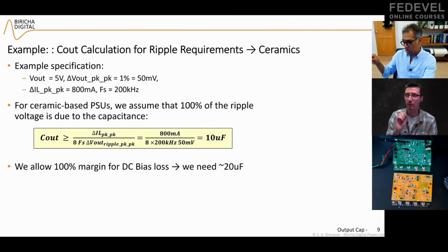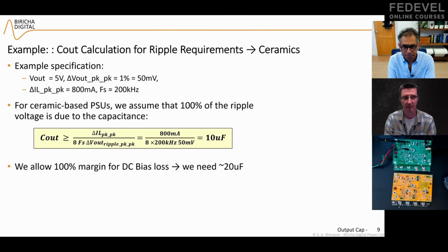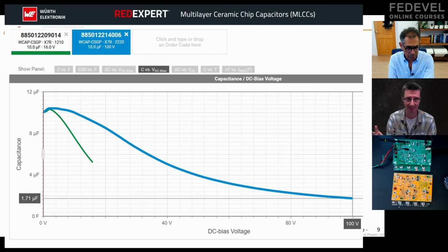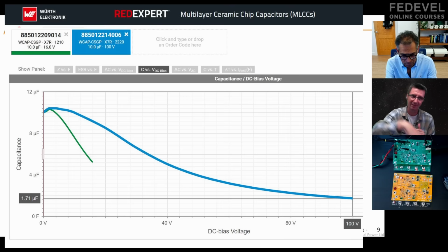Okay, I would like to add to these capacitors before you show it. If someone would like to understand a little bit more what we just mentioned, it's very easy to do. Yes. People can find a specific capacitor, and then there are some parameters. They can see there are a few graphs, and very quickly people will notice that if there is DC voltage on a capacitor, capacitance drops very quickly.